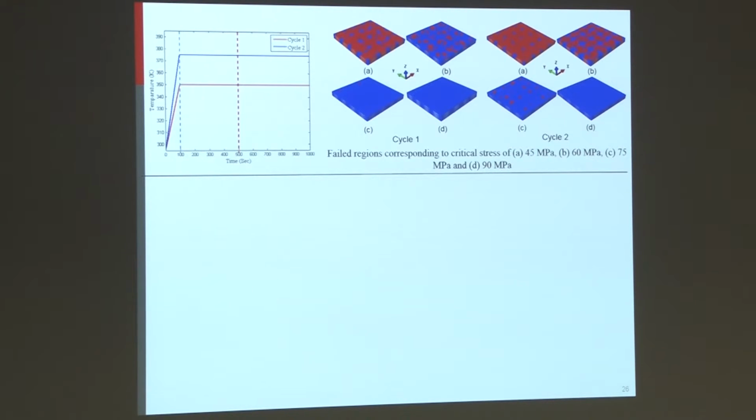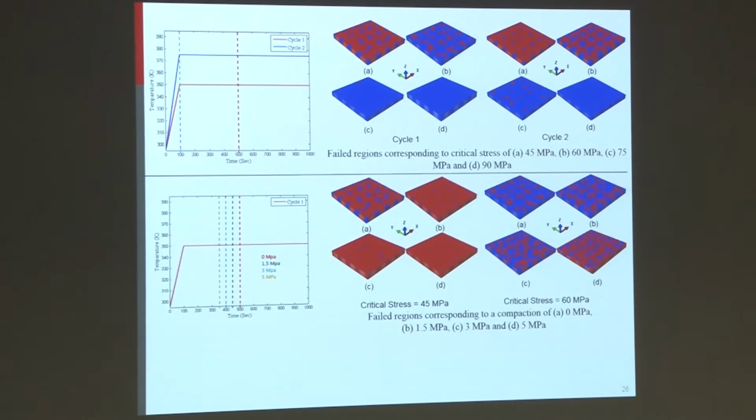We increase the temperature, we expect higher stresses, so higher damage could occur. But when we looked at the time required to achieve complete curing, we noticed that there is a huge reduction in the time required for complete curing. Now, so that's a trade-off. We know that some damaged regions may increase, but the time required for curing can reduce.